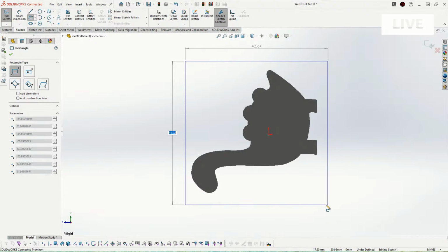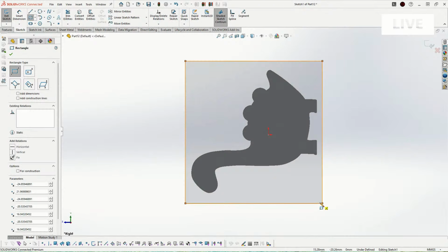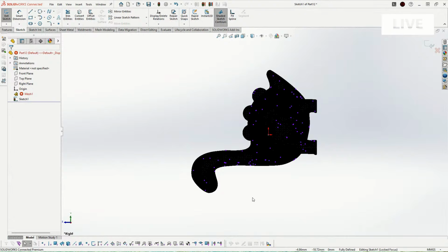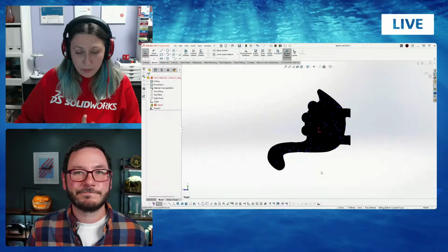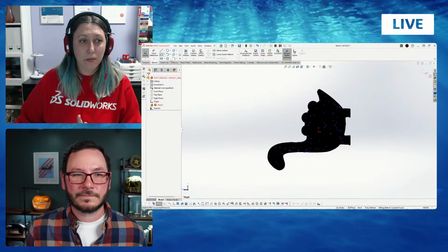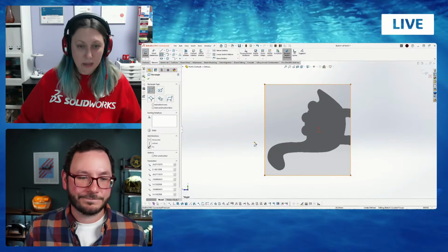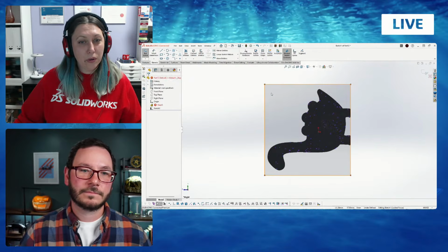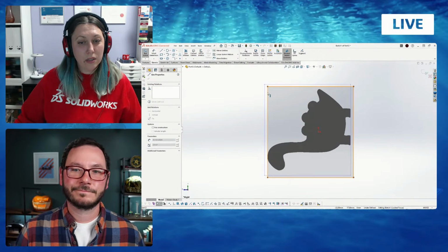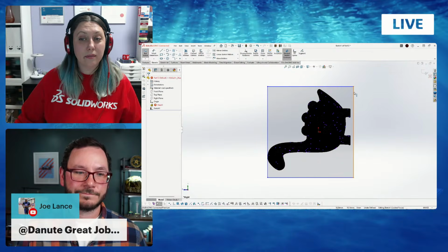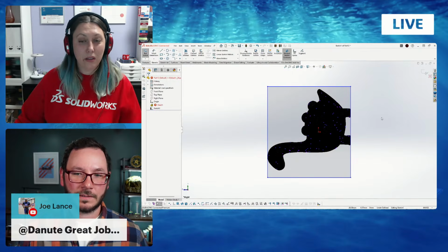But that's sometimes way too complex to deal with in SolidWorks. And as long as you have some slicing software, there you can scale it to a certain size. Because maybe that's one of the weak points of SolidWorks. You cannot scale to size. You can scale by percentage only.